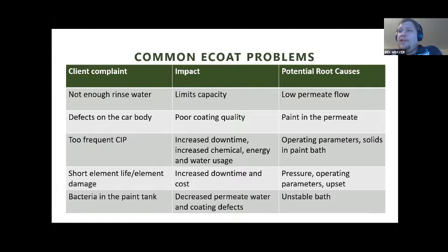One of the ways to prevent that is having a VFD or soft start on the pump. If we're using manual valves and you tell every operator to open the valve very, very slowly, well, the operators have 1,000 things on their plate. So any time they can save a little bit of time to move on to the next task, they'll do it. That's part of what they're trained to do. But opening up a valve too quickly can ruin a bank of elements.